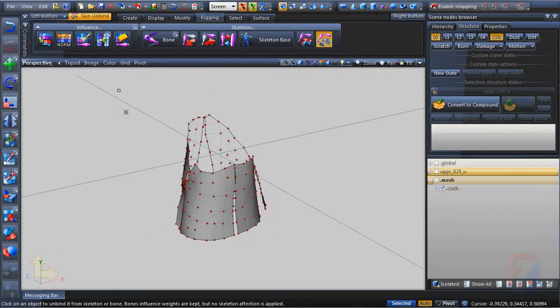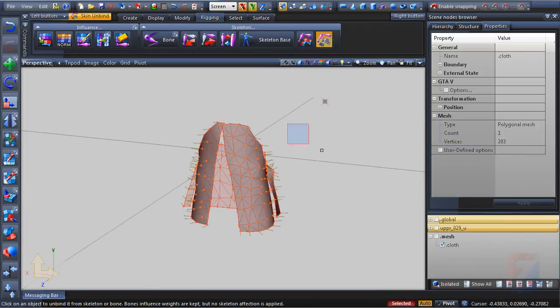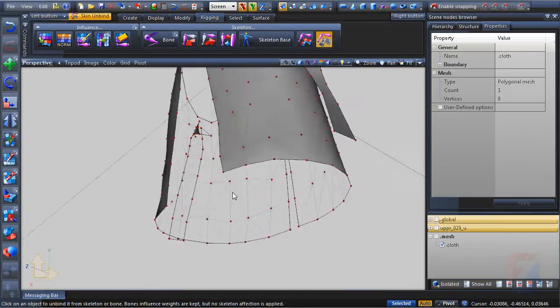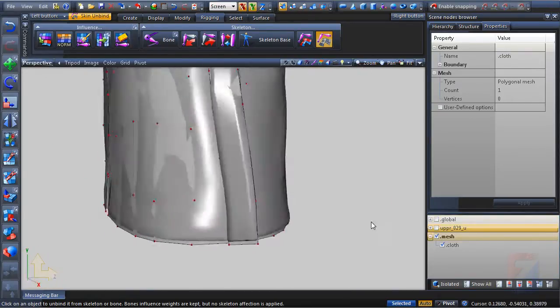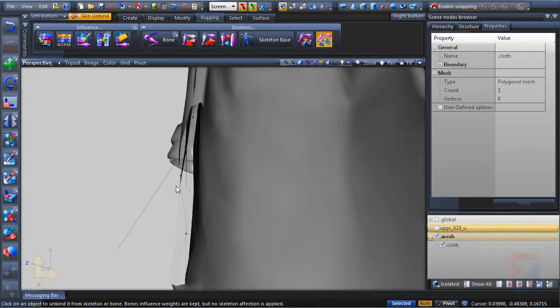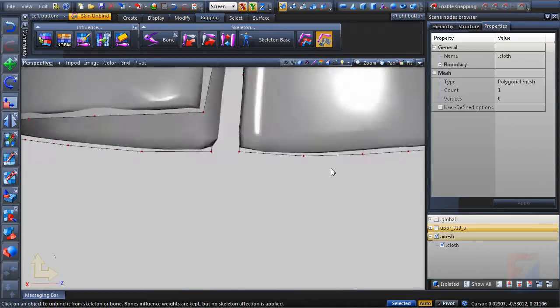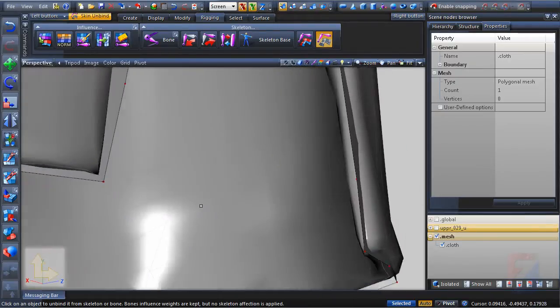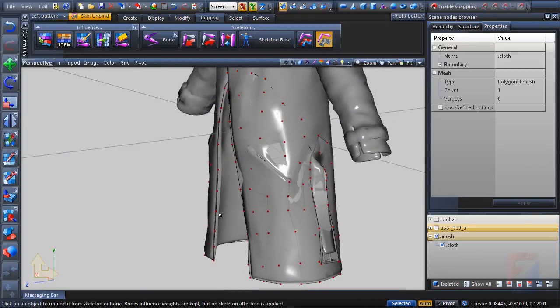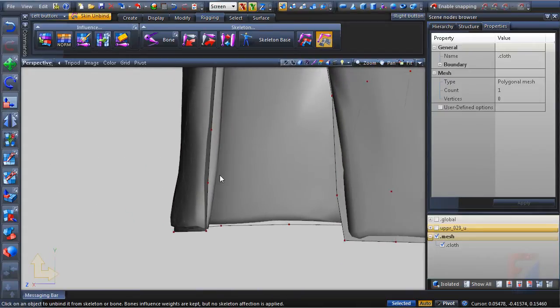First of all, I've told this already, we are constrained in a count of vertices. Also, it has to match the controlling object as much as possible. Another limitation, the controlled mesh should be pretty thin. This coat is pretty thick. For cloth simulation, it's not a thin drape, so it might have some artifacts, and you will probably see these artifacts.